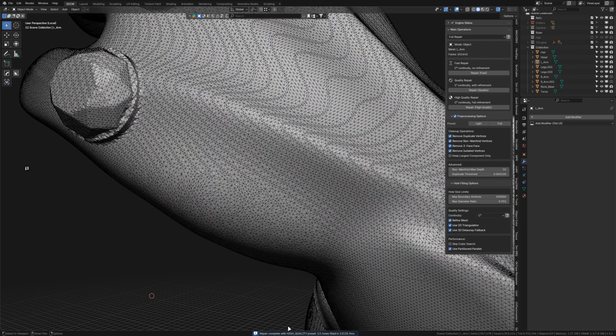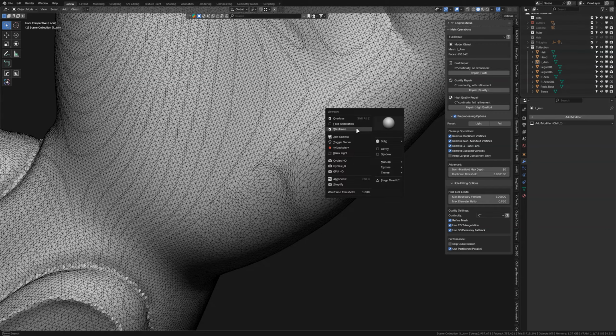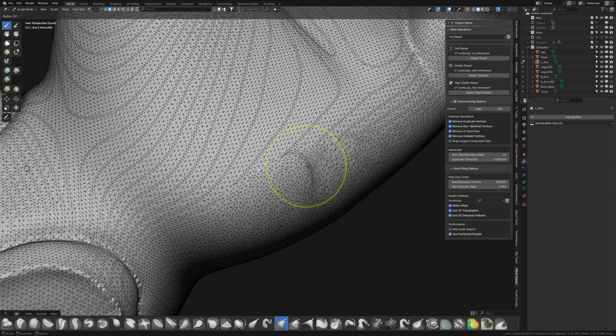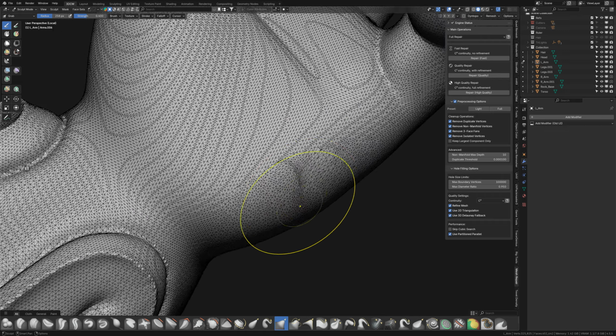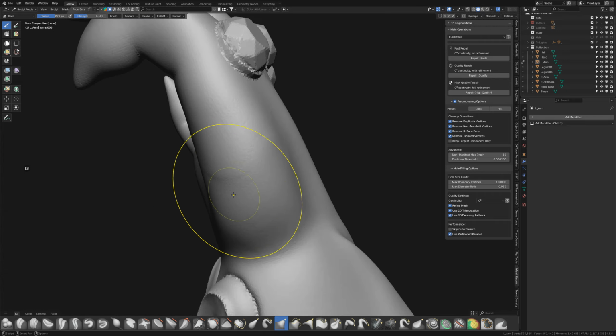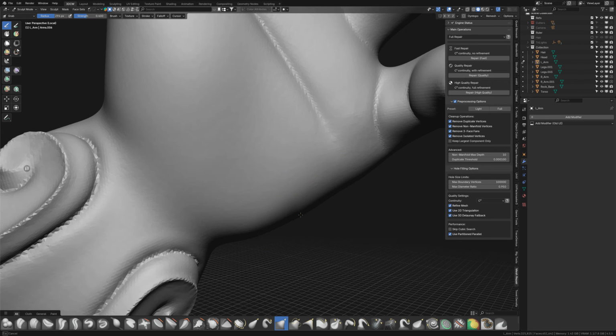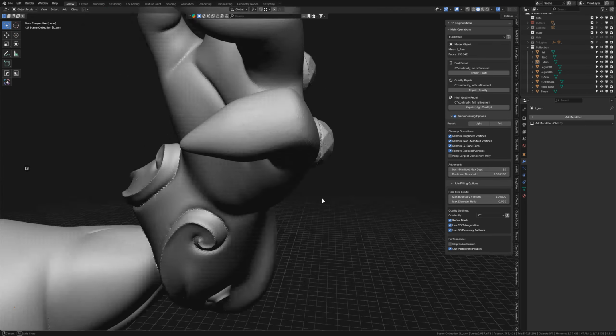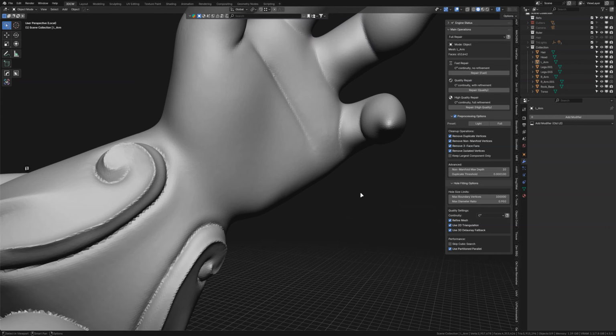So it did take some time, 13 seconds, because the mesh is a bit denser, but you can see how neatly it cleaned this up. There are some edges that you can just smooth them out with relax edge brush or just smooth brush. Currently I'm with my mouse, not my tablet, but you can see even if you printed this, you will hardly see it if you're printing this with FDM, and you almost have the same shape as before, barely any fiddling. And yeah, there we go, the hand is just patched.